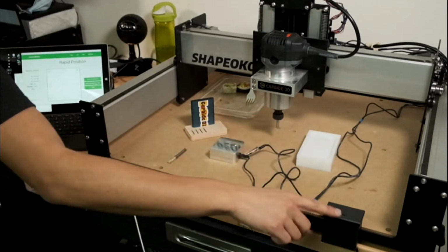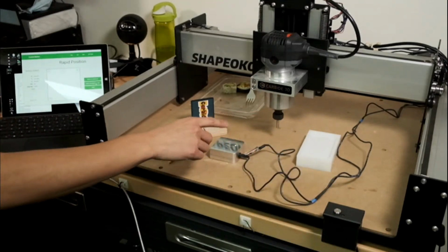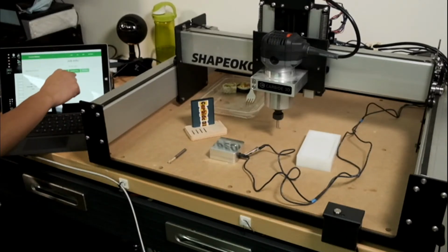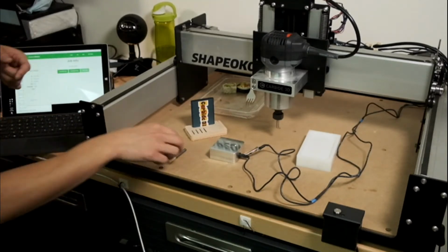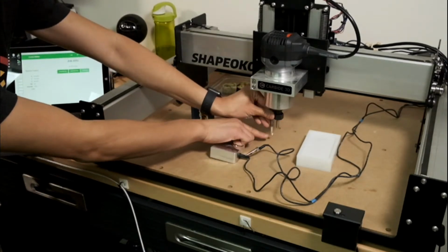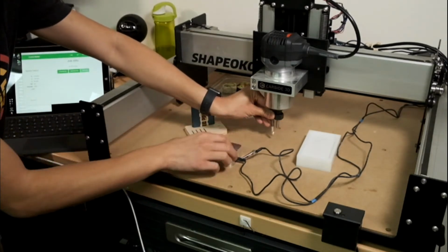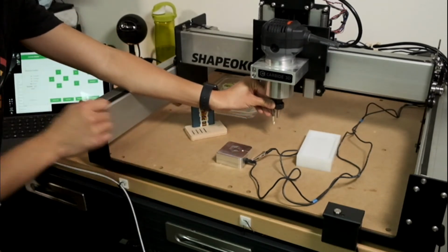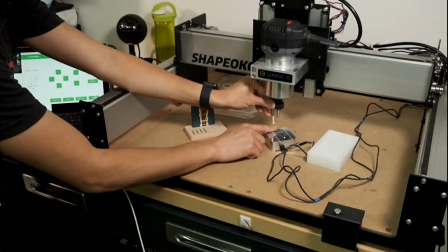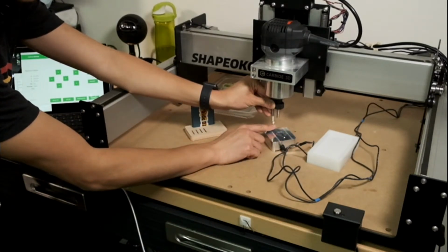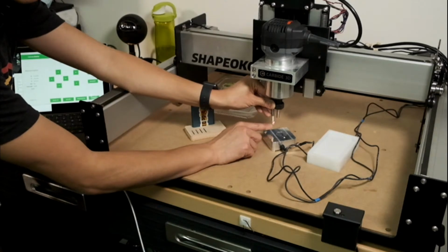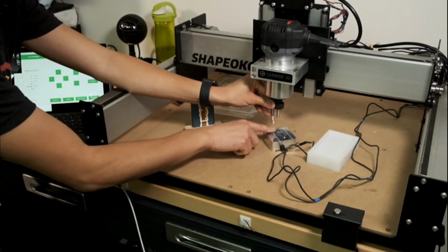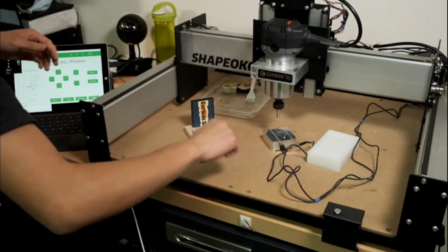So that's why you always touch off when you start. And if you change a tool, don't forget to go back to the interface and hit load new tool. Otherwise, if you load in a new tool, or you tip your end mill here and you're jogging around, you're setting a 0, and you jog this up and you say, I want this to be my 0, the CNC is going to think you meant up here, not down here. So every time you change a tool or this distance to your stock changes, hit that load new tool button so it recalibrates that.